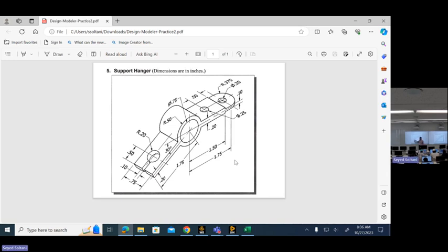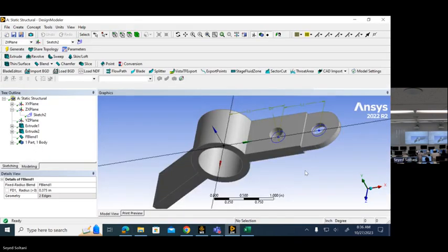So in order to create the circle and the rectangle over the same edge or the surface where it needs to be, we need to create a new plane and then create the new sketch within that new plane, which forms a 30-degree angle with this direction, the horizontal direction. And this should take care of the next step. All right, so this is how I'm going to do this.